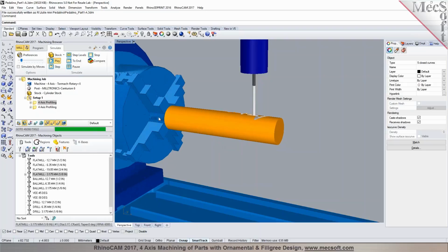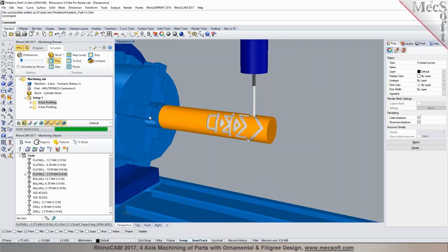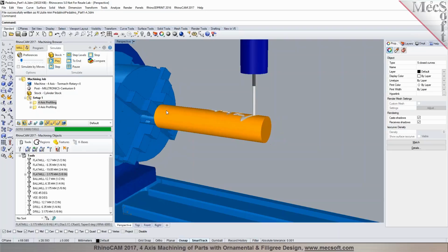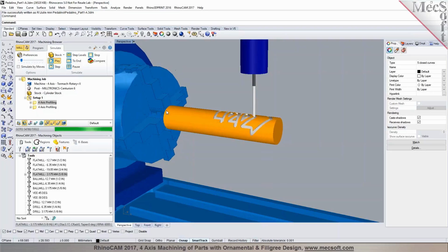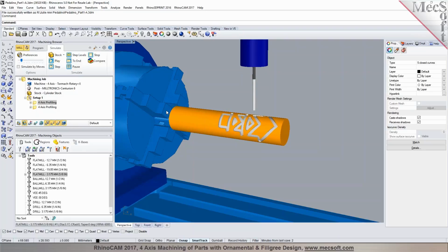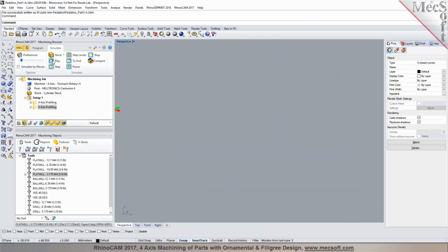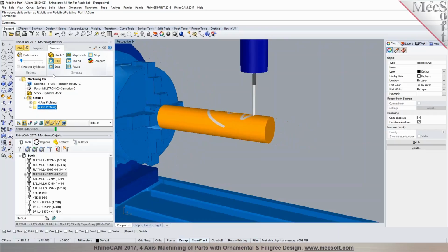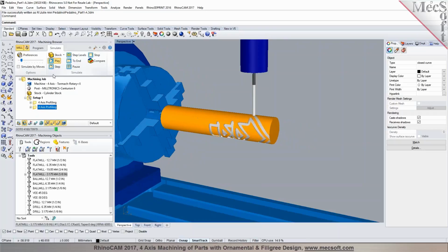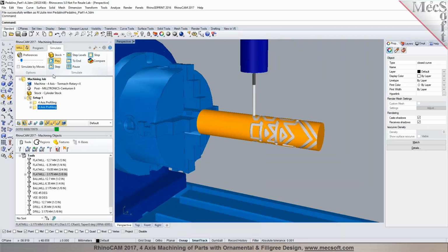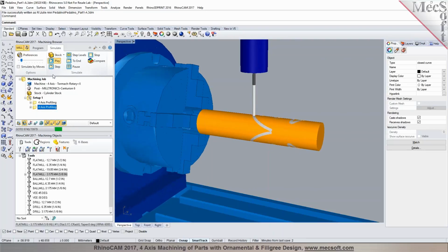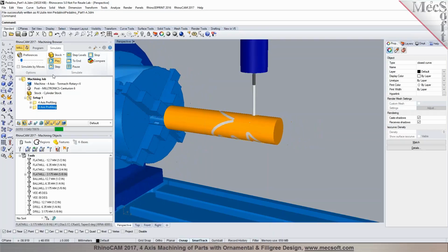Like you noticed here, I had to put the zero to the center, and then I actually put what is called the center of rotation to 0, 0. So we might be able to change it to the top, but this is just to show you how to run the machine tool simulation. Right. I don't have a 4th axis on the Miltronics, so we're doing everything in Mach 3 just to figure out the software part right now. Okay, makes sense.